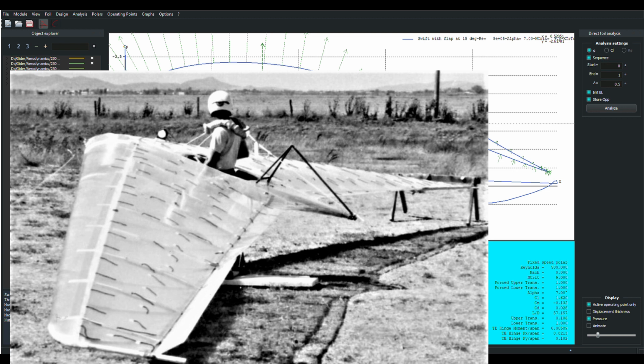And it looked funny, but it's really what works out best, because as you begin to deflect the elevon down at the root end of the elevon, the way that the flow conditions are, you're not really asking the flow to go around a corner until you've deflected the elevon down about 10 or 12 degrees.